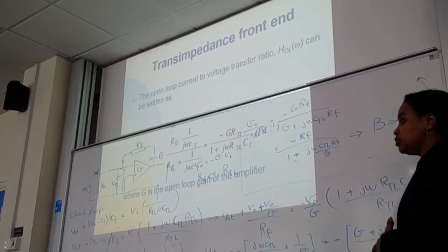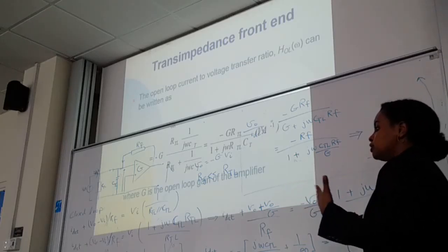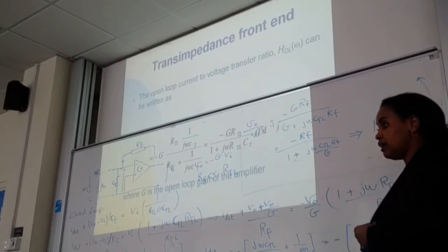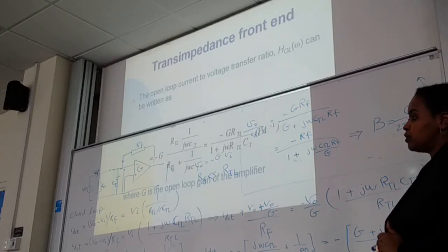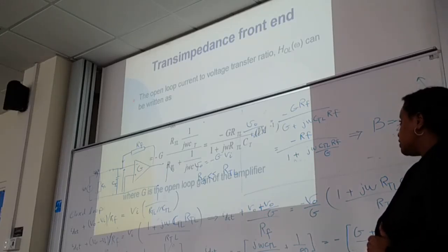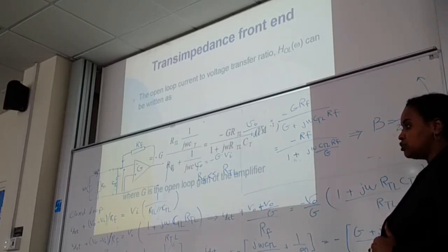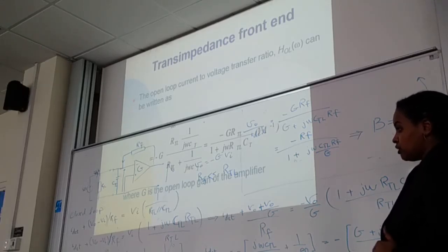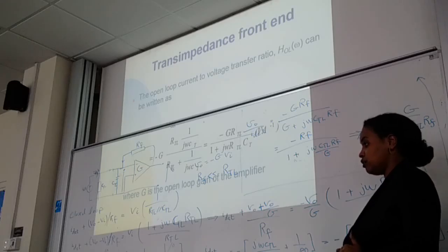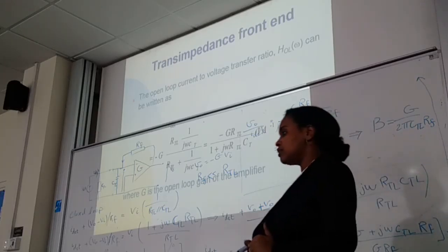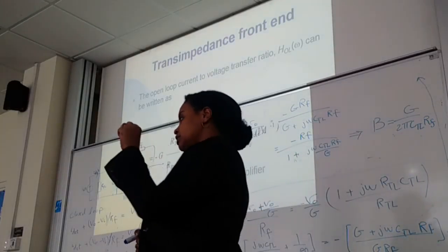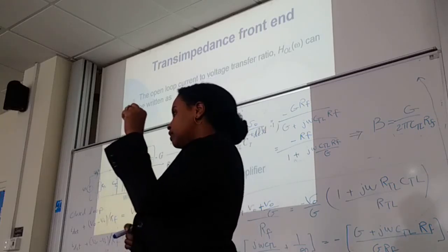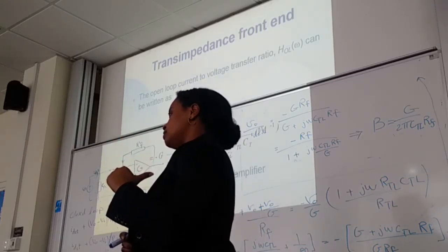In the high impedance, we were free to increase R and compensate with equalization. Here, because of the stability issues, we cannot continue increasing RF. That's why the sensitivity for this structure is lower than with the high impedance.